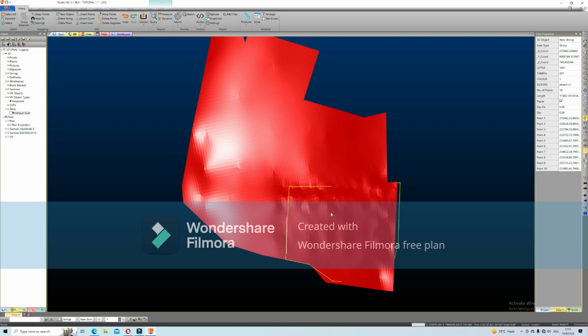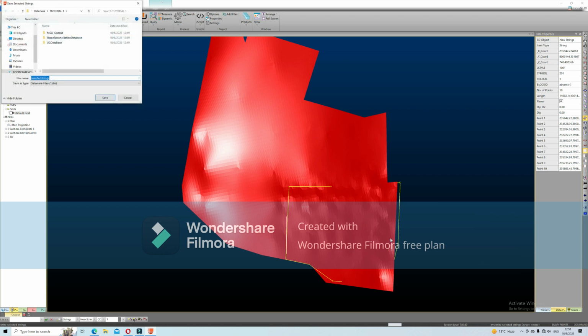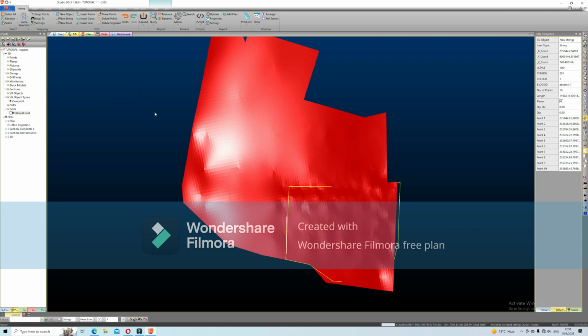So this one is the boundary. This string now becomes the string boundary for your whole design. So I'm going to left click on the screen, then I'm going to save this string as the design boundary. Then I'm going to save this file.